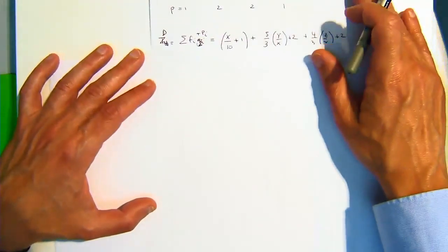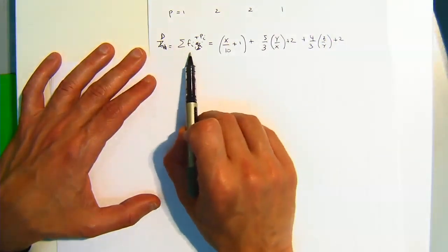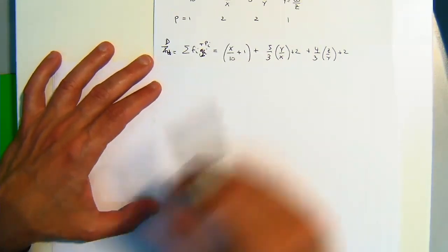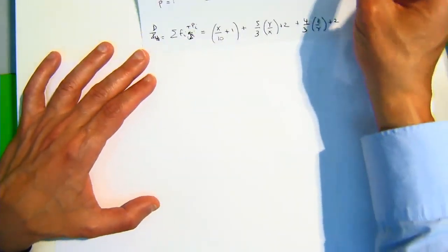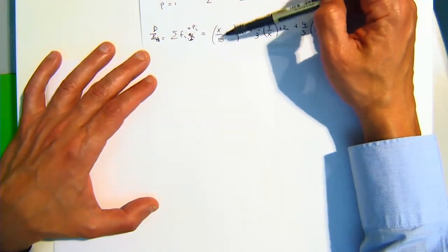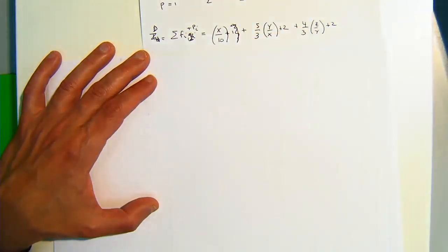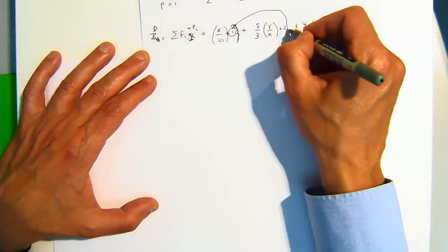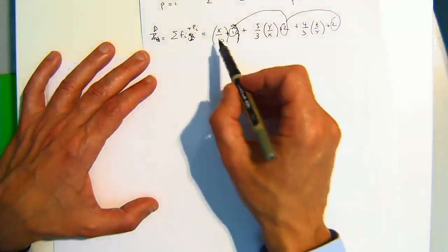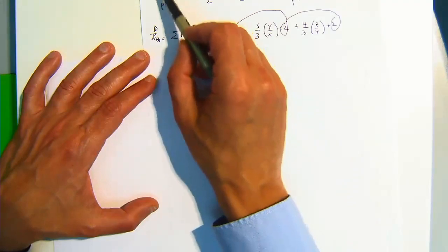Okay. So the delay, as we discussed, is D equals F_i plus P_i. All right, and essentially all I'm doing here is working out, I should write it like that, otherwise you might get confused, these are the parasitic delays, and essentially what I've done is the logical effort times H1.